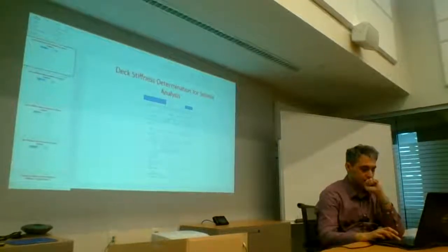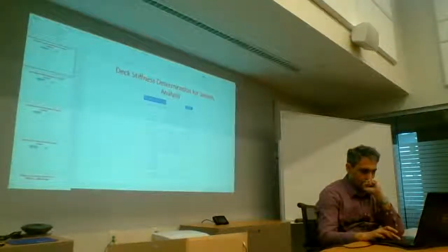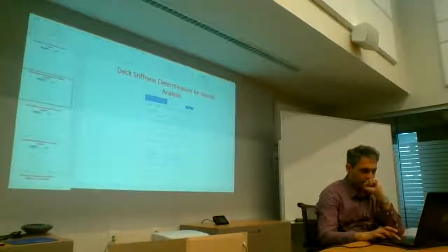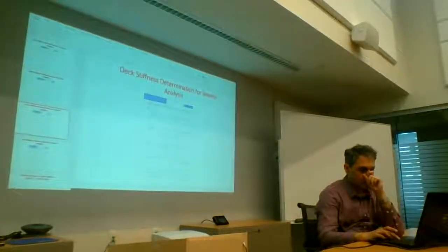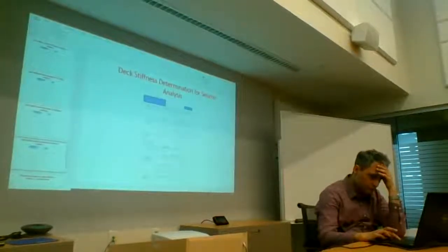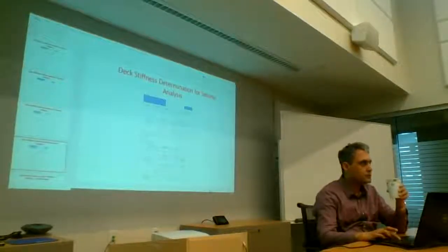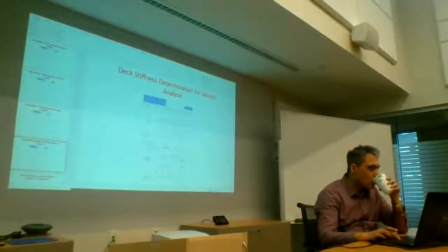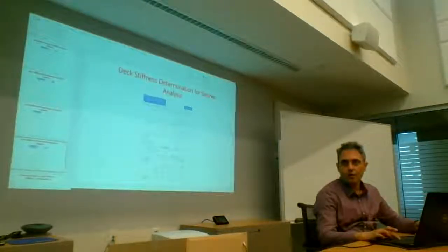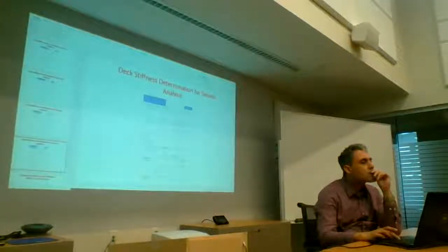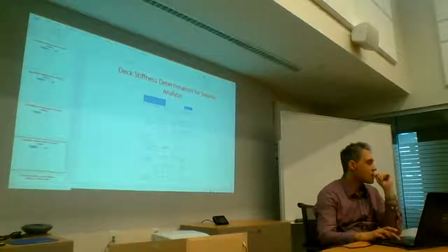But I don't think anything. There are a few things, like in slabs, you're right. The specific type of slabs with decking and all these things will not get modeled there, because SAP does not have the capability to model that. It can do layering and all these things in layers, but not with that deck shape directly. You have to do that through CSI detailing and all these things. Yes, you have to do that part manually. I agree with you on that part.